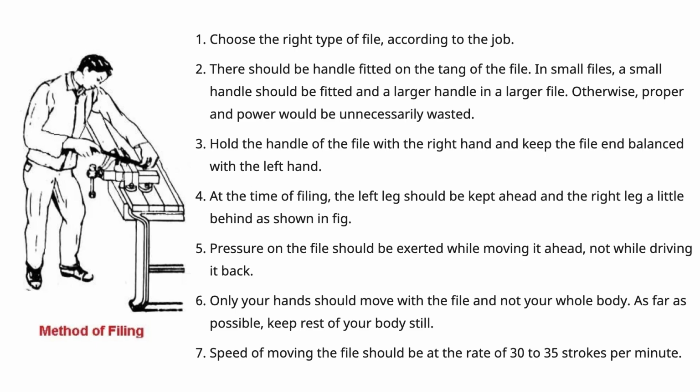So basically choose the right type of file according to the job. There should be a handle fitted on the tang of the file. In small files, a small handle should be fitted, and a large handle in the large file. Hold the file in the right hand, and keep the file in balance with the left hand. At the time of filing, the left leg should be kept ahead, and the right leg behind, as you can see in the image.